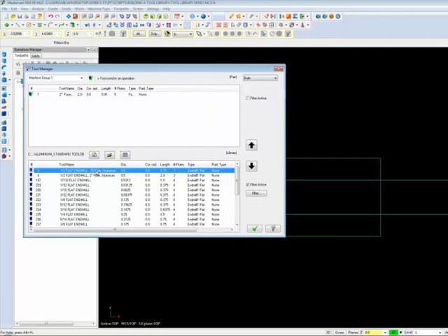While it's easy enough to change existing tool geometry around to create new tools, how do you create tools that Mastercam doesn't have a standard definition for, such as the thread mill we created in the webinar before Christmas? One fairly easy way to do that is to import tool geometry, if your tool manufacturer can supply it. If not, it's possible to create your own tool geometry and use that to create the tool profile.